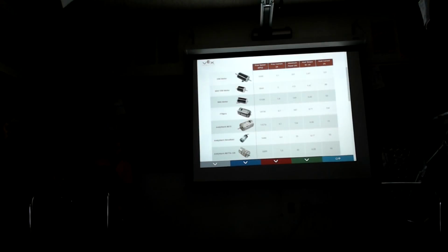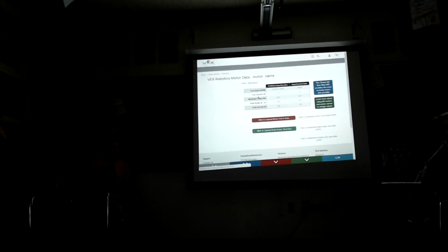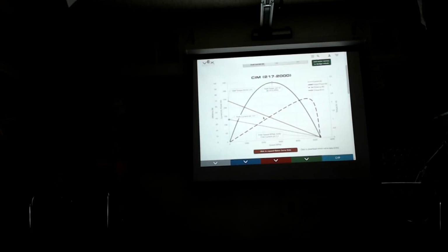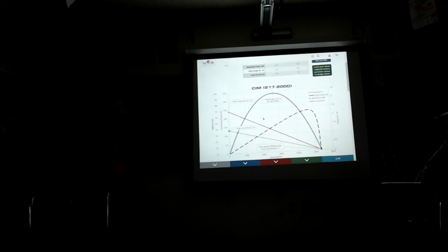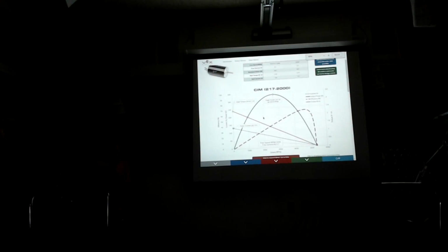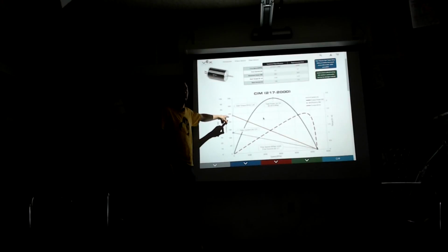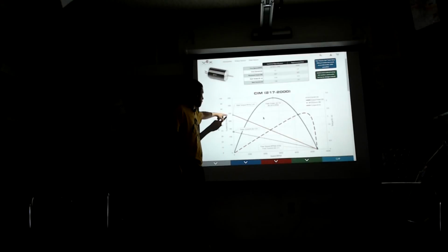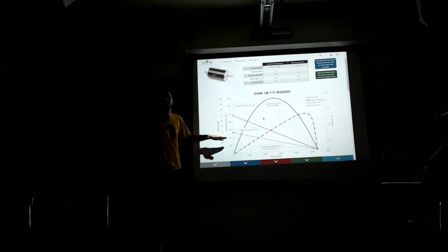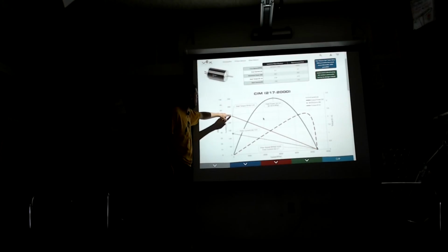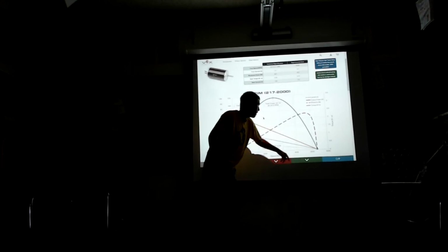One of the cool things we can drill in on, so let's go look at a sim in a little more detail. Okay. So we can actually see this graphically. This is representing the equation that we just derived in a different form. This whole chart's assuming you're applying 12 volts to your motor. So we can look at torque as a function of speed.